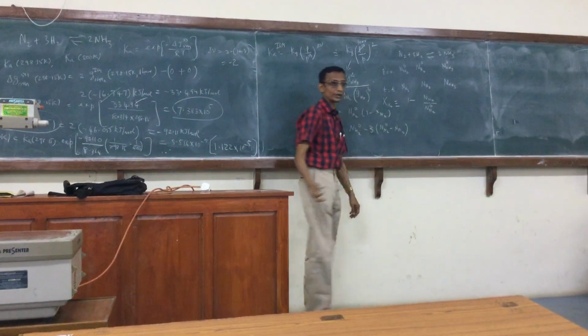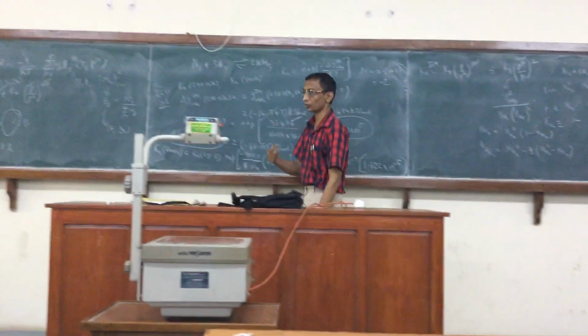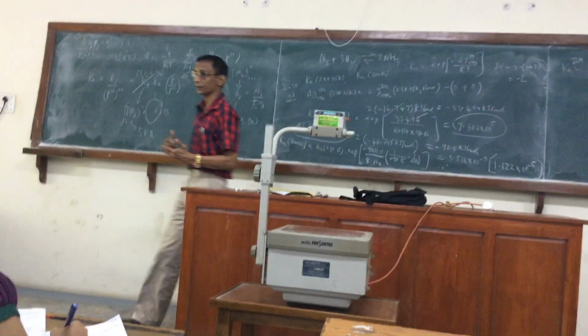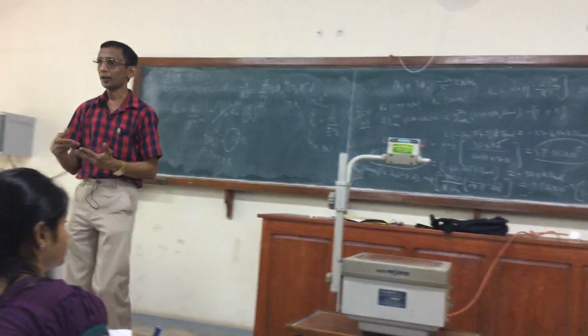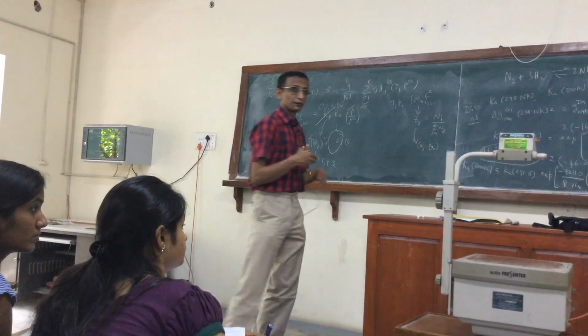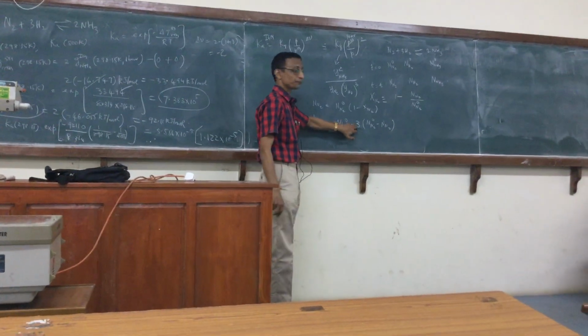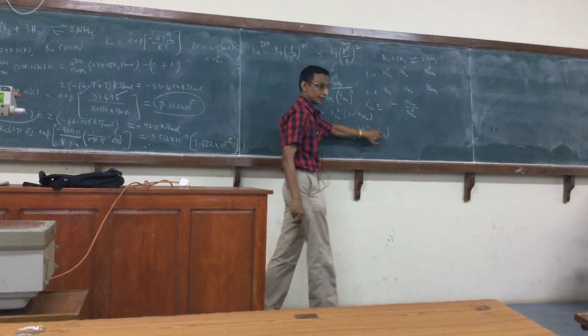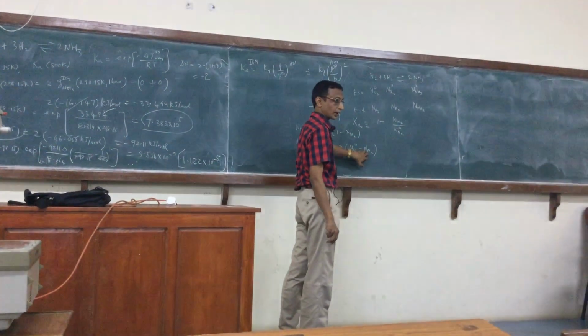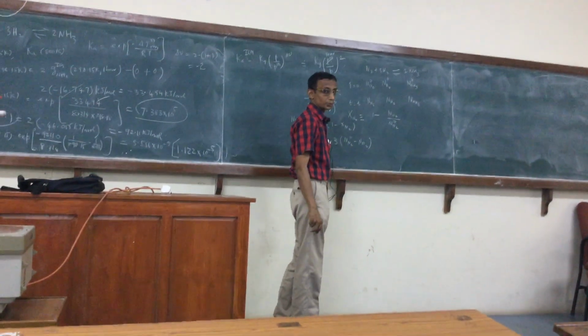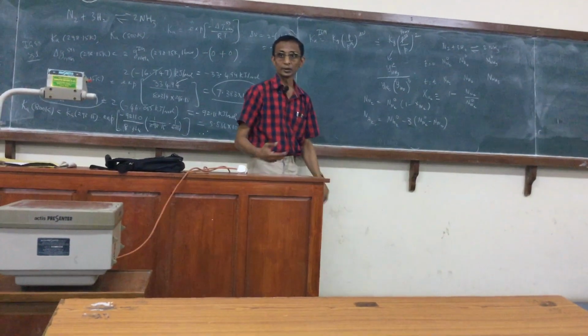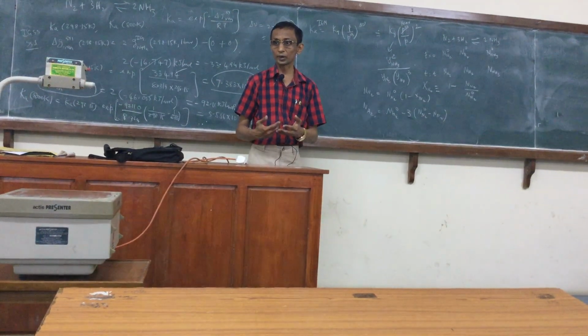So that's the easiest way to remember. The number of moles of hydrogen, or any other component other than the one I have chosen to define the conversion, would be, if it is on the reactant side, the initial number minus the number of nitrogen that has converted times the stoichiometric coefficient, because for every mole of nitrogen, 3 moles of hydrogen would have reacted.